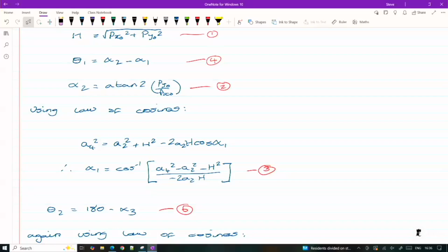Or you can do the solution in MATLAB and come up with a table of angles that you can put into the Dobot. So you can simply say within the Dobot algorithm, set joint 1 to 50 degrees, joint 2 to 30 degrees, joint 3 to 20 degrees. And you've calculated those angles within MATLAB, for example.